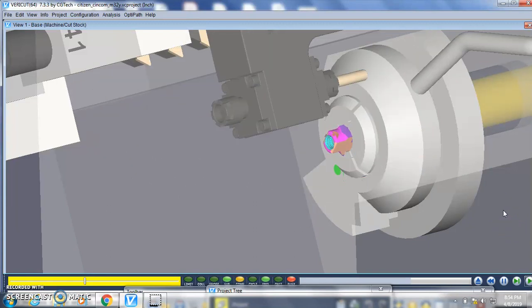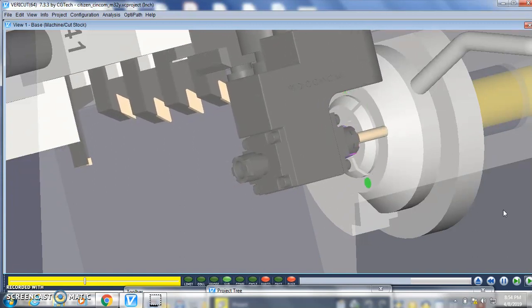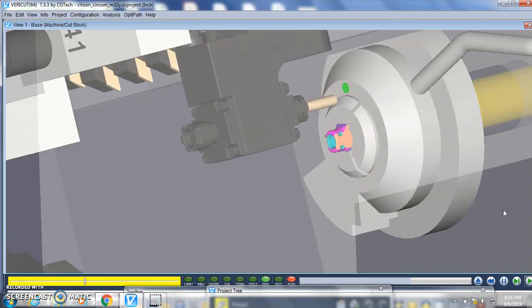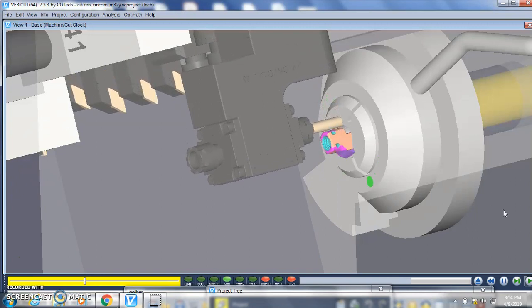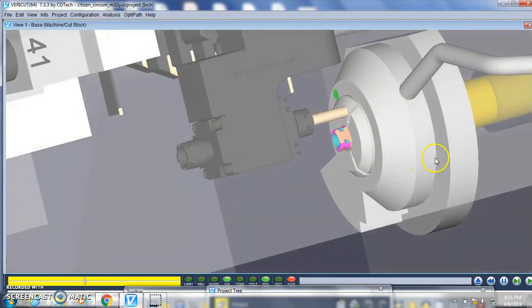One critical aspect of multi-channel programming on a multi-axis machine is how robust the post is. These simulation packages are designed such that when you post the tool path out to the control, it will simulate exactly what will happen on the real CNC machine. So if you can look at the